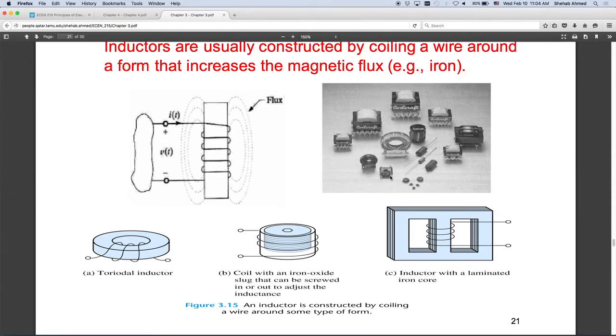Sheet of steel for a magnetic is basically an electrically conducting material and a magnetically conducting material. Steel is electrically conducting and magnetically conducting. In this case, you have a magnetic material that is seeing a time varying flux. It is also electrically conducting, so you will have current flow in it because it's nothing but a sheet of steel. It's like a closed loop, right? So you will have small loops of current flowing in this material, causing losses, right?